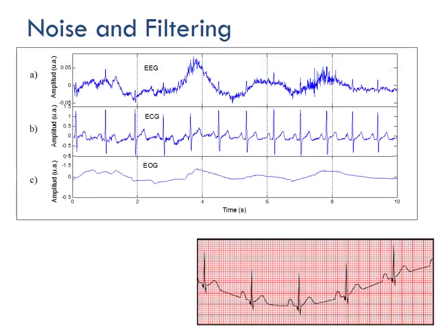So here we have three different biomedical signals: EEG, ECG, and EOG. EEG is electroencephalogram. That is a signal that essentially comes from your brain. In layman's terms, it's reading brain waves. You can see that signal is very choppy. There's a lot of different noise inside of there, and all that choppiness is noise caused by a bunch of different reasons. Sometimes it's caused by external factors like a cell phone going off, or the 60 hertz power going through your house. But it also can be caused by the signal reflecting off your skull.